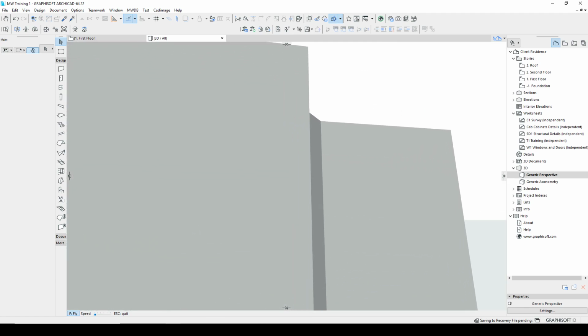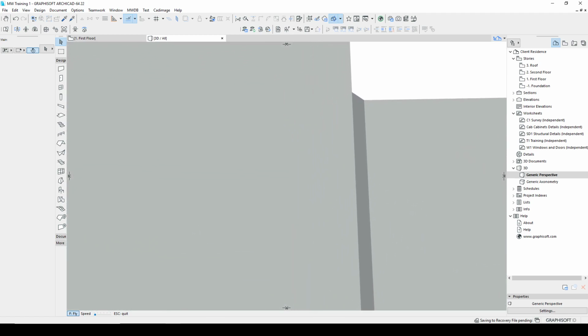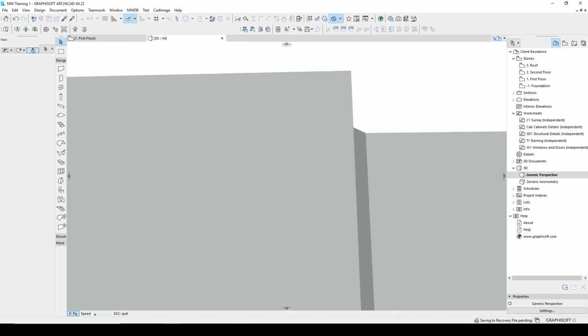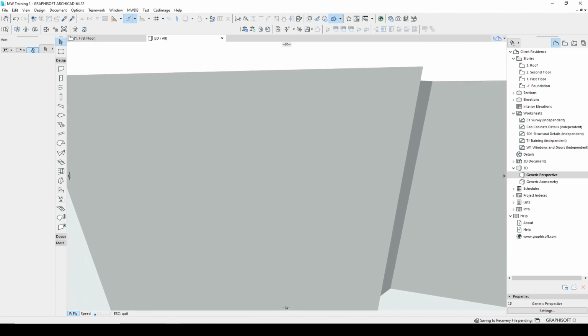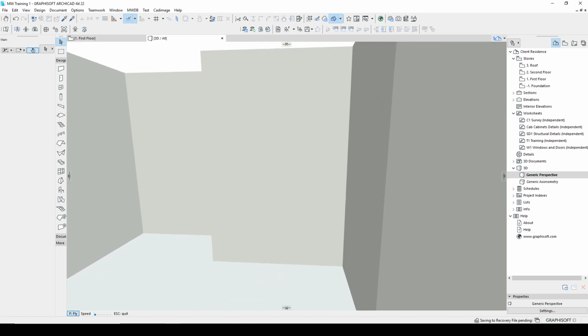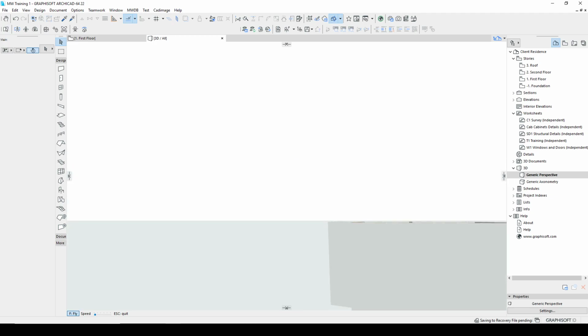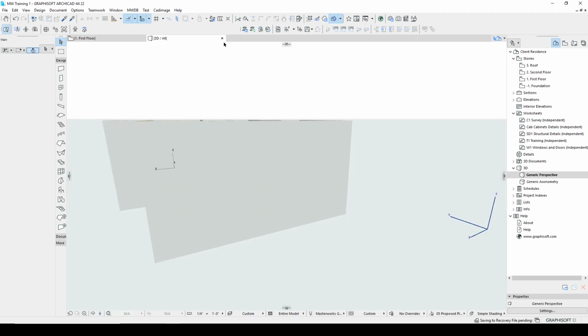And often, especially for interior shots, you're going to need to get into the building. This is the best way. Page up and page down move the camera up and down. So this is a nice way to explore the building. So that covers some of the basics of moving around in 3D, and you'll very quickly become accustomed to it.